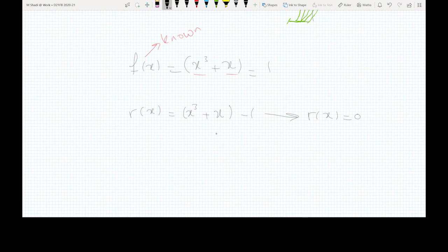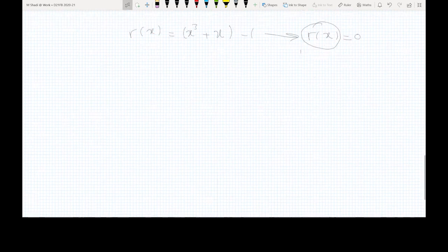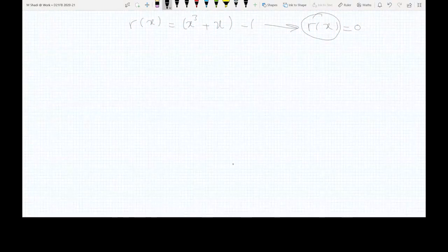All right, now this would become easier if we do an example, but I'm going to get into an example later on. Making the residual function equal to 0 is basically the essence, the heart of any iteration algorithm. So all iteration algorithms will try to make the residual equal to 0, and there will be different strategies. One of the most efficient strategies is Newton-Raphson, and I'm going to discuss Newton-Raphson today. There will be other algorithms, but Newton-Raphson is very popular with the finite element method, and this is why I'm strictly discussing the Newton-Raphson method.